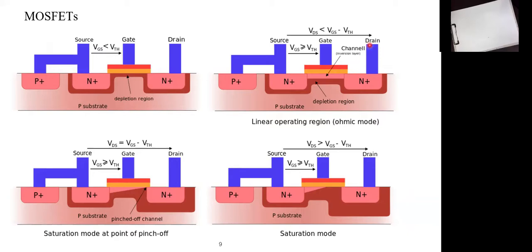So in this stage, the current is directly proportional to the drain voltage. You increase the drain voltage, so more attraction force, so more electrons come from the source to the drain, so more current. Okay, but at a certain point, which is the pinch-off point, you tend to have a channel with a zero width at this barrier point.